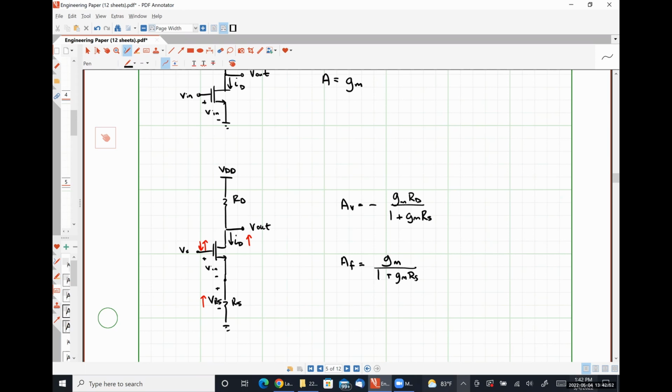So while we don't explicitly see a direct connection, the effects are the same as if we had a negative feedback network, okay? Effectively, we have a feedback network that contains an open circuit from the output down to here, and then a resistor from this point to ground. That's how we're going to start looking at feedback networks in a little bit.